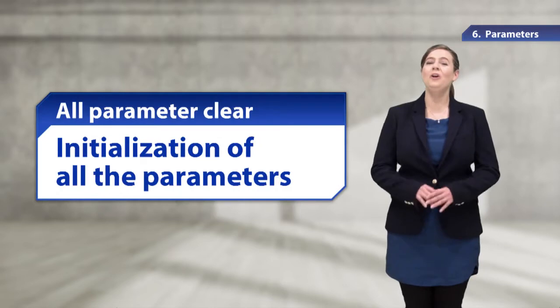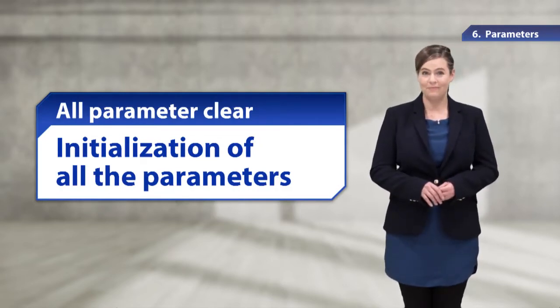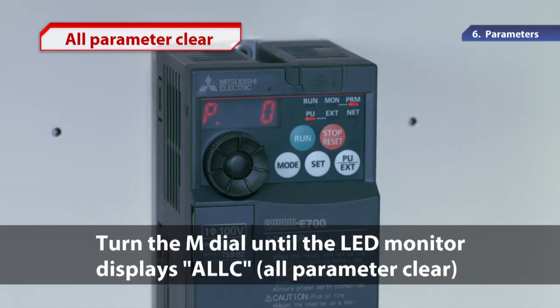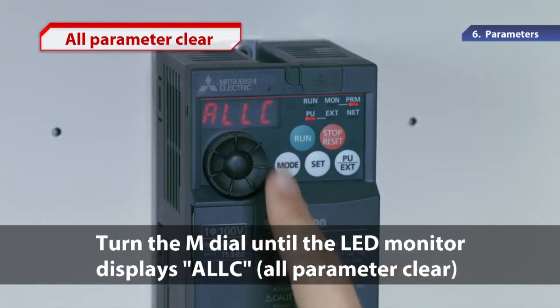Let us begin by initializing all the parameters. This is called all parameter clear. Please take the following steps. First, press the mode button in the PU operation mode to choose the parameter setting mode. Turn the M dial until the LED monitor displays ALLC, all parameter clear.